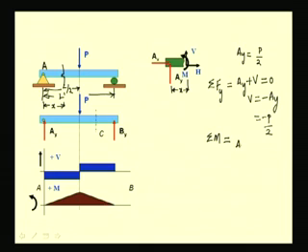So, we have Ay whose moment arm is x and the clockwise moment, so it is negative, and we have this moment m which is positive equal to 0. So, we get m is equal to Ay times x, which is P by 2 times of x.